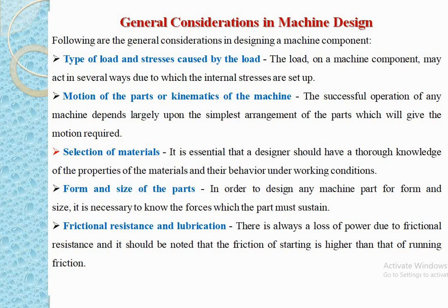Suppose we apply a tensile load on a component, then due to the application of the tensile load, there is an induction of tensile stress in the component, and when that component fails due to the tensile stress, then we have to design that component by considering tensile stress as the criteria of the design. That's why we have to consider the type of load and stresses caused by that load while designing a particular component.